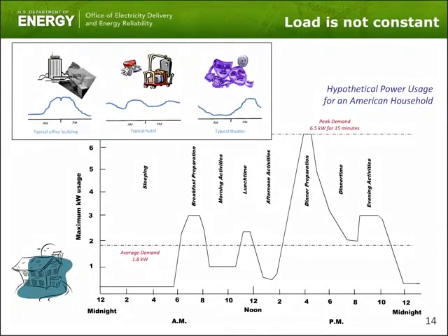And so as you look across other areas, for example, the office building, the hotel, and the theater on the top left, there are differences both in terms of the shape and magnitude depending upon what type of user you are. So for example, an office building will tend to have a profile that's higher in the middle of the day and might drop off a little bit at lunchtime. A hotel might have higher usage as people are doing laundry in the early evening or the night, so it might have a different characteristic. And then a theater, of course, with shows in the evenings typically, might have something that goes later into the night.